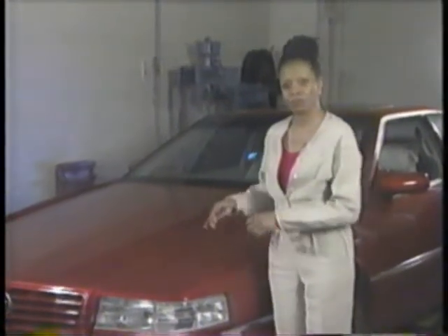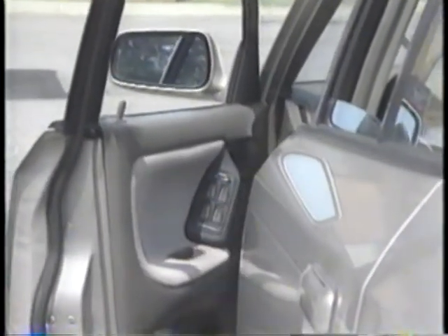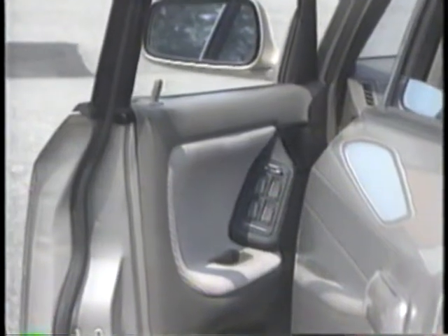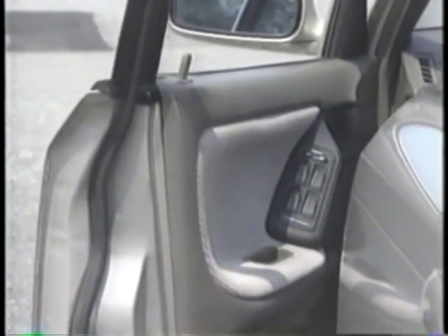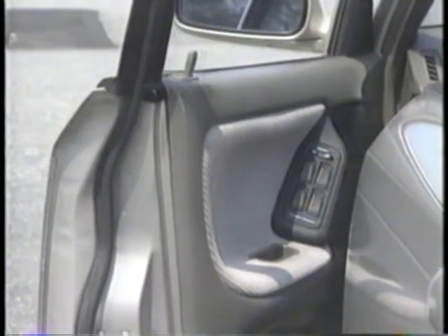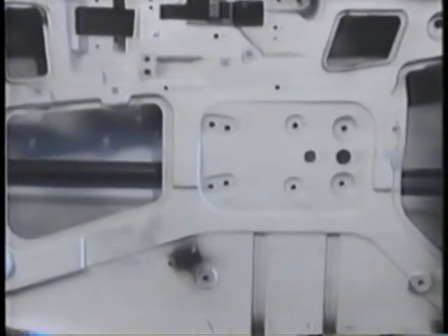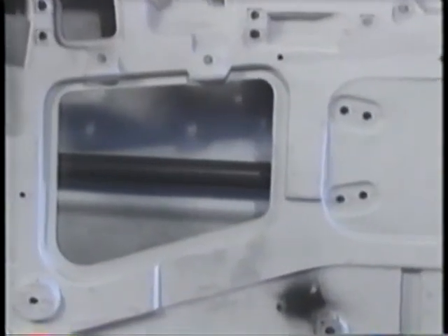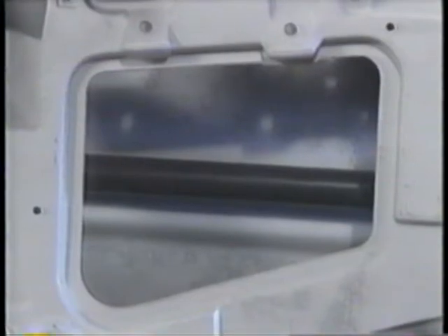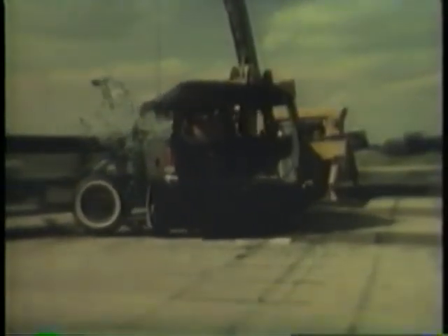While a vehicle may crush to absorb frontal or rear impacts, occupant protection in side impacts requires a different approach. Since there is very little crush space between the outside of the door and the occupants of the vehicle, the doors and related hardware must be as strong as possible to prevent the crash from intruding into the passenger compartment. This is achieved by reinforcing the doors with a high-strength steel barrier that spans the width of the door. In combination with anti-burst hinge and latch systems, this reinforcement spreads the force created during a side impact over a greater area and into the door pillars themselves.